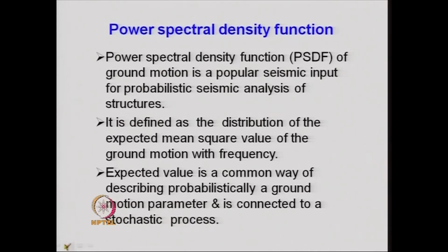It is a very popular seismic input for probabilistic seismic analysis of structures. Now the definition of the power spectral density function of the ground motion is a very simple definition, but it requires some understanding of the random process.